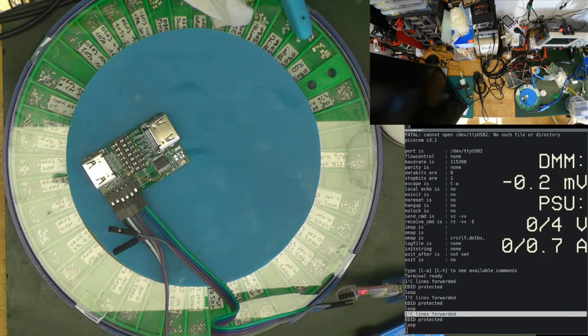CR1 here. Pull up. Okay, so we don't want a pull up. Although it would be 100K pull up, but we don't want a pull up. So we disable the pull up. Disable pull up. This also puts it in open drain. Yeah, so it's okay. And just right afterwards, we switch to input.